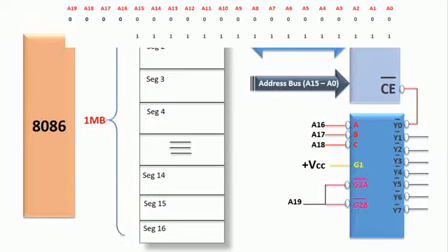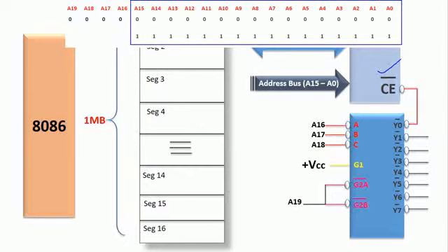Look at this. Okay, so whatever the memory device we are having over here, what is our interest? Our interest is based on this connection, this particular memory device is mapped into which segment is the question. Now in order to know that, first you are supposed to focus on the address lines. So what are the address lines which are interfaced to the memory device directly? 16 address lines. They are varying from A15 to A0.